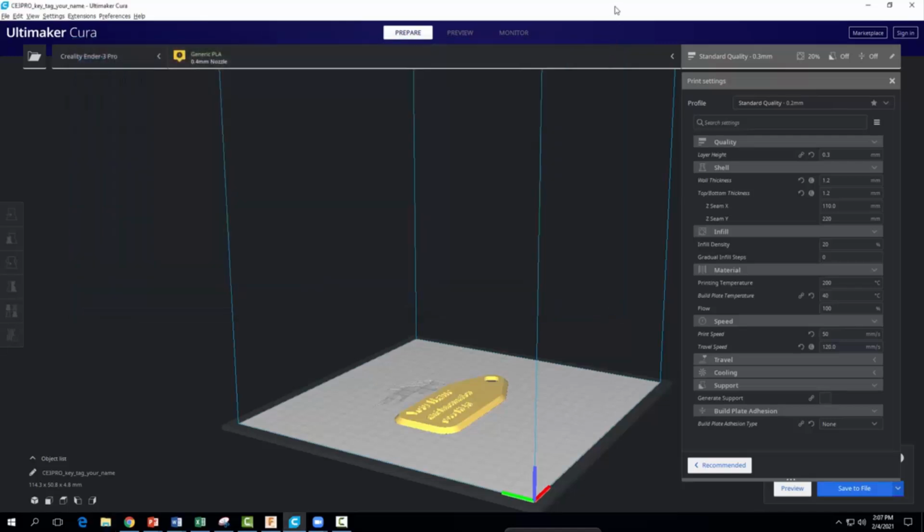Once you've successfully verified that your G-code file is on your SD card, go ahead and remove it. When you're finally ready to 3D print, make sure your bed is level and make sure you know how to operate the machine. If you need any help, please come talk to me. I'll be more than happy to come and assist you.